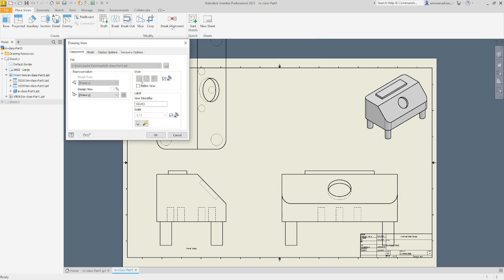And then up here you can see everything is currently grayed out because everything wants to remain the same as the base view, because the base view is kind of like the parent, so it wants to stay the same as the parent. But I can hit this check mark here and tell it not to scale from the base, at least for this one, and say, hey, I want this to be a little bit smaller. I want this to be like a quarter of the size.